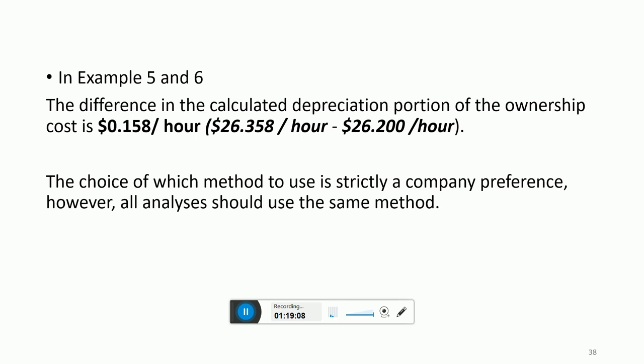However, ownership guarantees control of machine availability and mechanical condition, but it requires a continuing sequence of projects to pay for the machine. Ownership may force a company into using obsolete equipment, as they don't have the new equipment, but as they own the old equipment, they have to use it. So the calculations applicable for determining the cost of direct ownership have to be developed based on all these things.